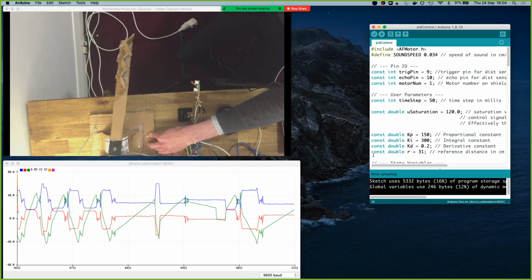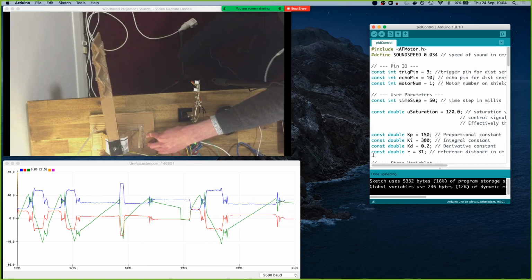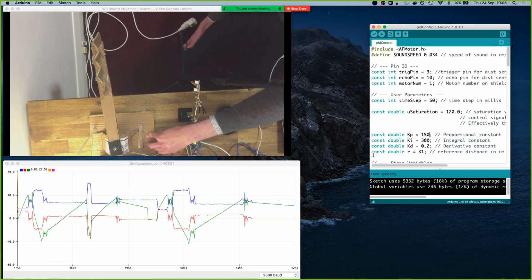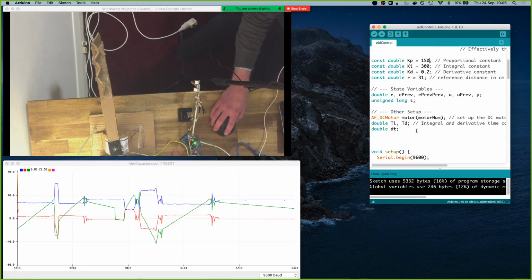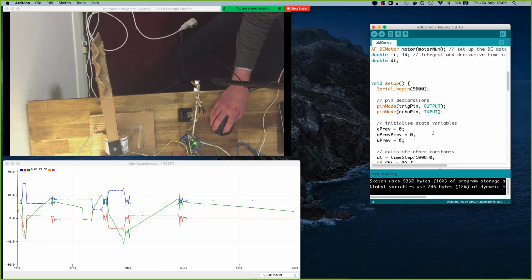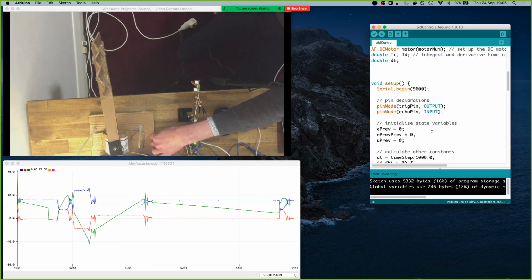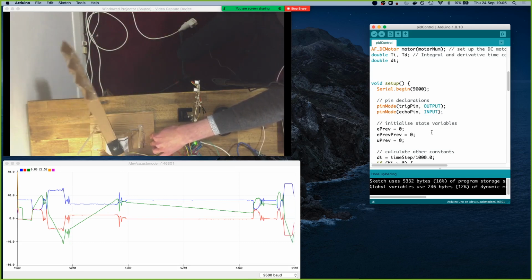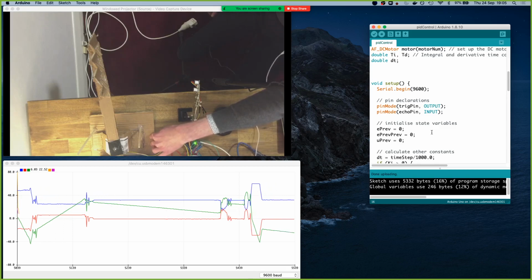It's just off the topic of using an actuator constraint of the motor. Maybe something that might make it look more responsive is to figure out the minimum voltage required to start moving. Yep. So we set that as 1, and then just use a multiple of whatever that minimum term is. Yeah, that's a good idea. So you'd say only kick in above that. Right now, what I think I'm seeing is there is voltage coming in, but it isn't high enough to see any movement. So by the time it starts moving, it doesn't adjust in time. I think it's because of the weight and the friction of the motor, meaning that it doesn't move. Whereas if you find that minimum movement, you start seeing more dynamics.